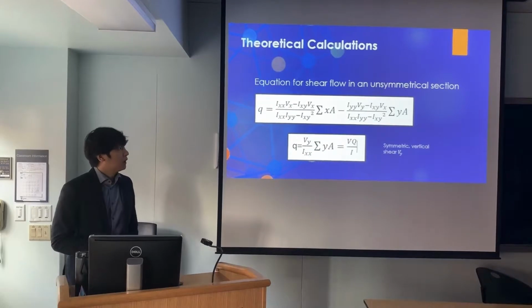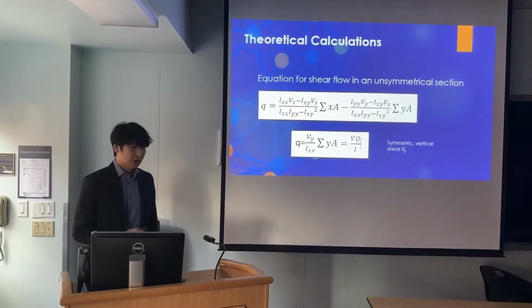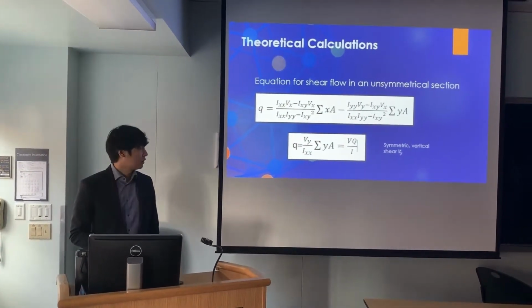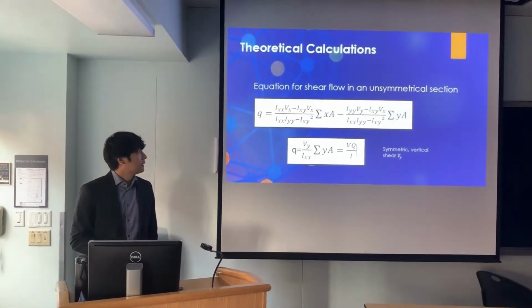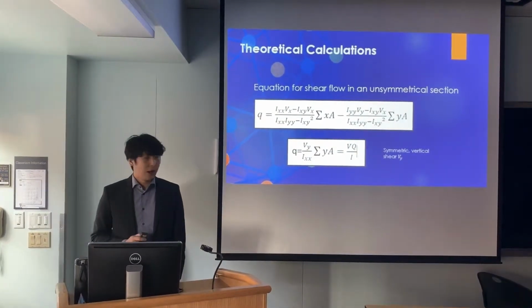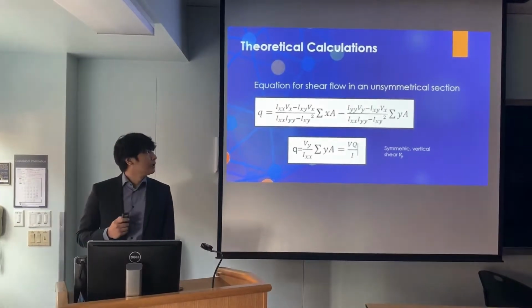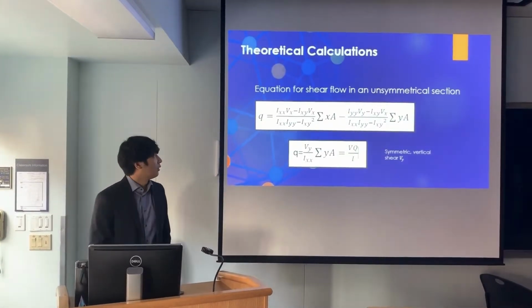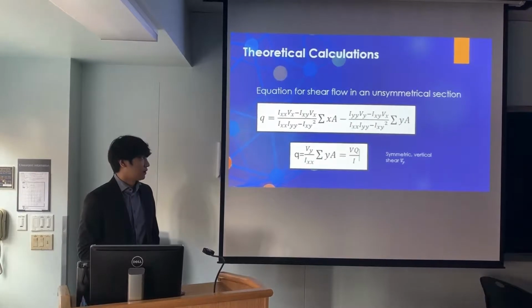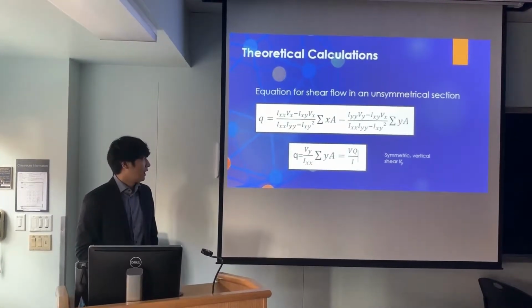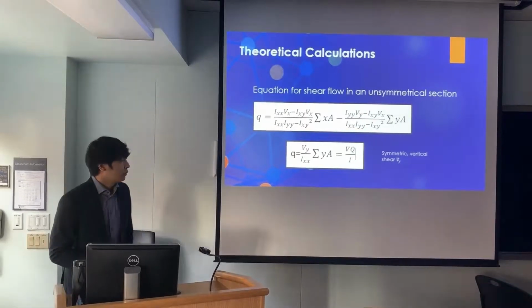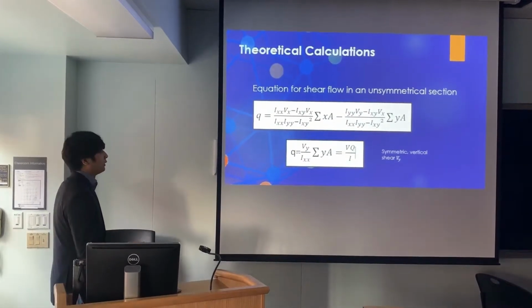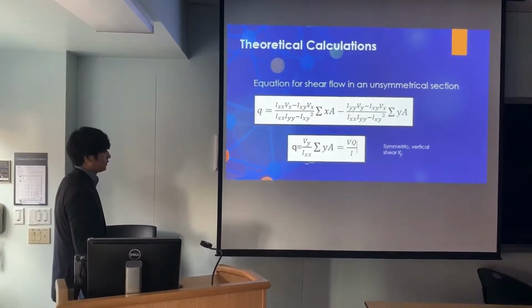We need to apply the shear flow to calculate the shear center location. Because the C beam and L beam are symmetric, the product of inertia Ixy will be equal to 0. So the equation will be simplified to this equation.